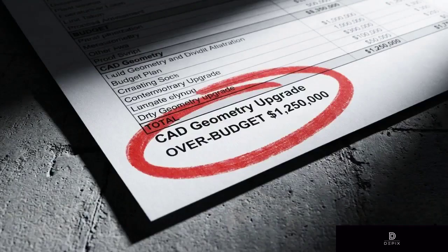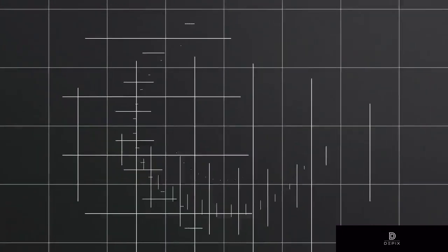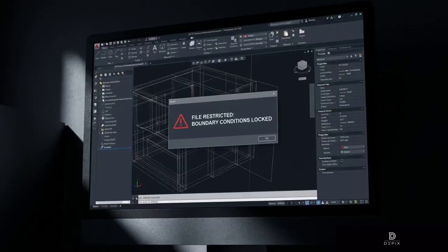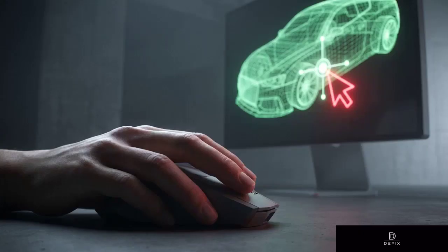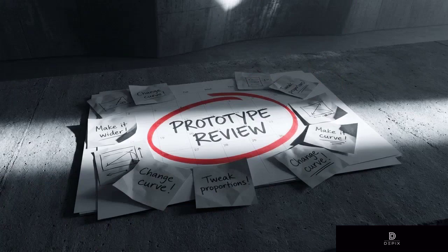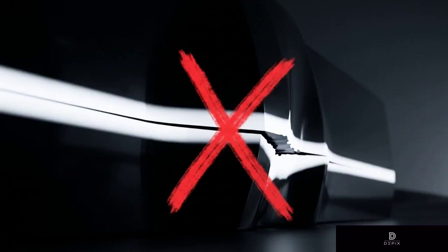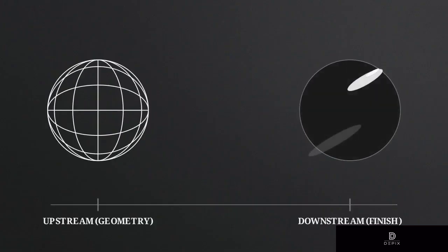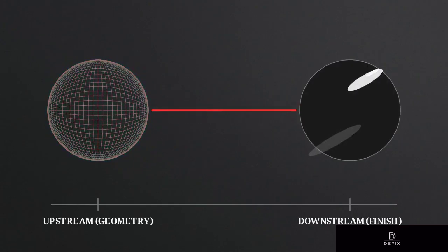Upgrading that existing model to G2 causes a cascade of costs. The surfacing team has to generate an explosion of tiny patches to maintain tighter boundary controls, resulting in a heavily restricted, fragile digital file. Demanding higher continuity makes the 3D model incredibly rigid. The geometry becomes economically disastrous to alter at the exact moment a product program is most likely to request late-stage proportional changes. The jagged reflection on the final product is not a mathematical error. It is a process failure, caused entirely by allowing a downstream material decision to quietly dictate an upstream geometric standard.